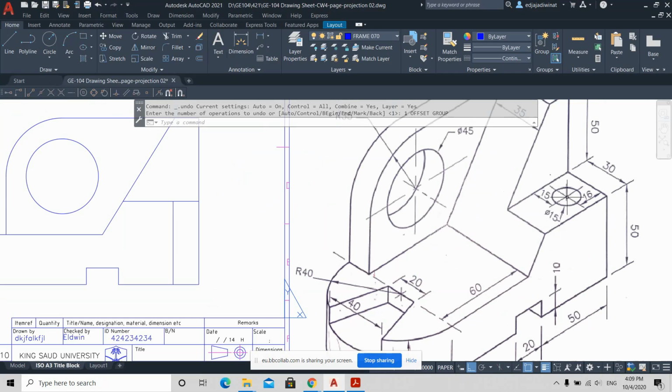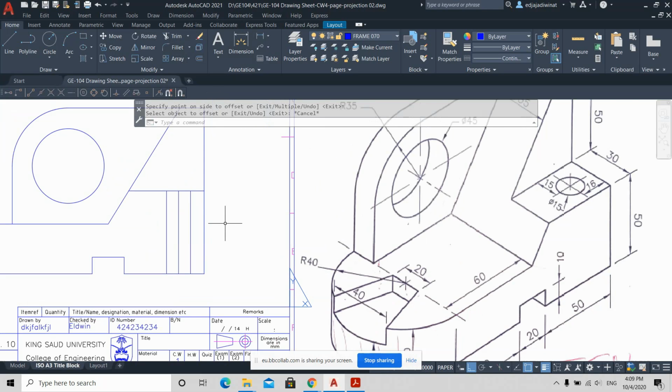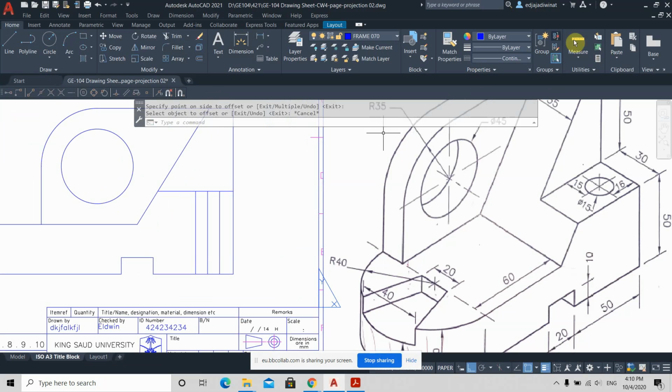So that means you can offset the center to the right 7.5 and to the left 7.5. I can do that. Offset 7.5. Okay. Goes there 7.5 and there 7.5. So now you are sure the distance is 15. See, 7.5, 7.5. Okay.